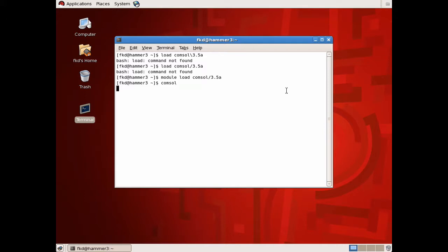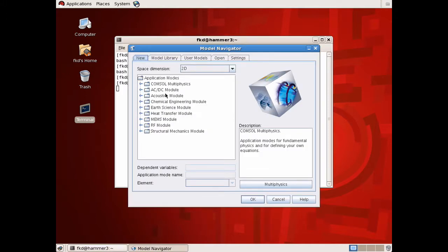Thinking. So, what do we know? Okay, so I guess what we know is that we can deal with multi-dimensional problems using this advective component. The mechanism by which we do that is exactly the same as for transient problems for diffusion, except we have this extra advective term which gets added into the conductance matrix. Depending on our choice of time step and element size, we may have some issues with stability, which we can explore.